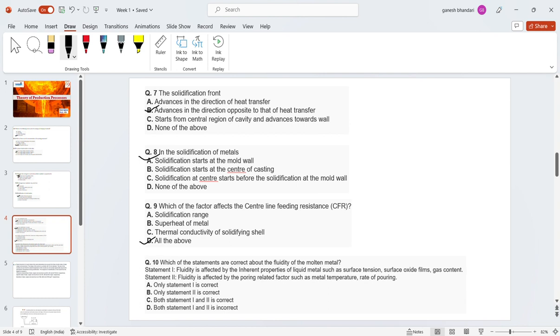Suppose you have a solder ball, at your surface tin oxide and lead oxide are present, while at the core molten tin and lead are present. Tin and lead will melt and come into liquid state, while your outside won't come into liquid state. It will remain as tin oxide and lead oxide. Both are highly stable.